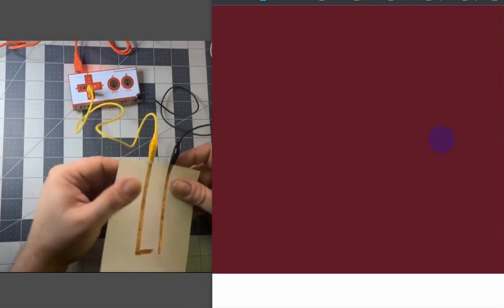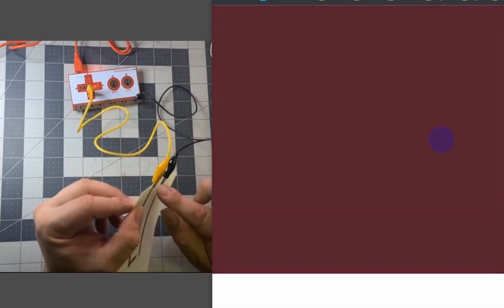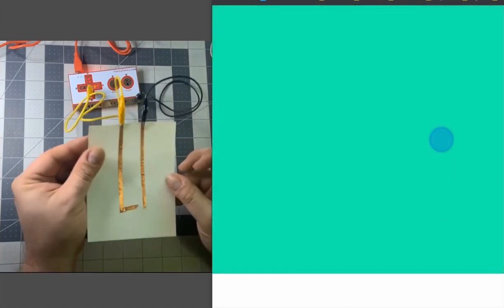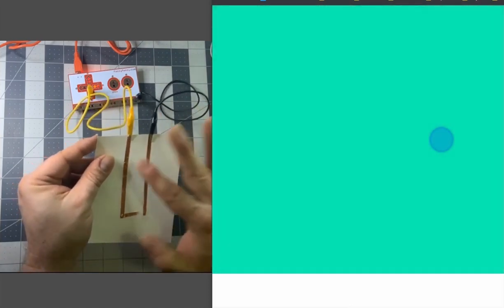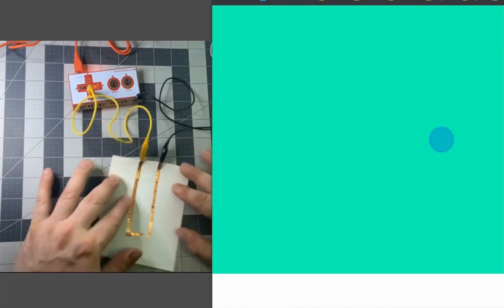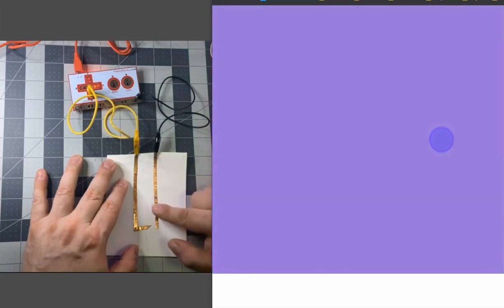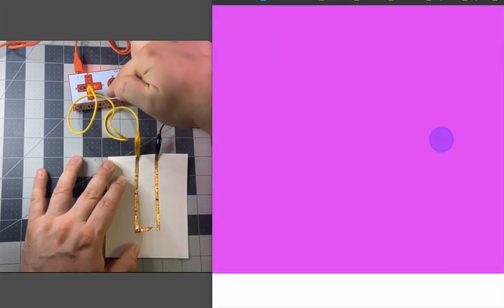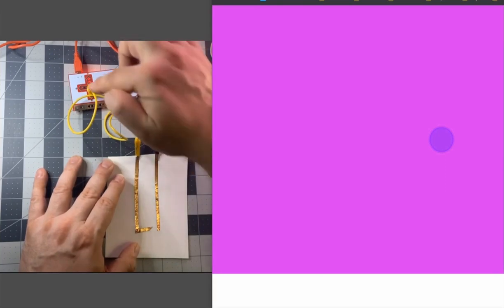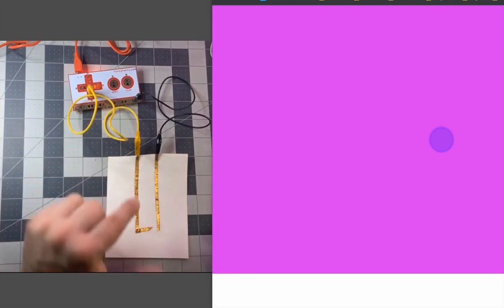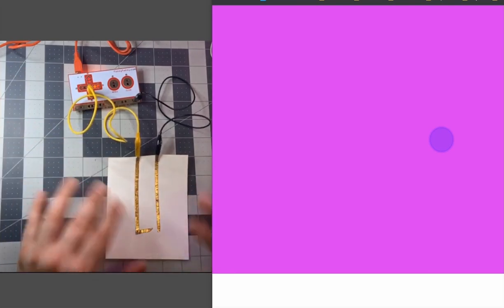Okay. It's also important to understand that the teeth in those alligator clips dig into the copper. And no matter what material we use here, we should be able to do that. So from this, what we could actually do is create multiple buttons that are connected to the ground. You only need one ground wire, and that's why the earth on the Makey is one long one. They're all connected, but each of the keystroke buttons is its own circuit. So as you touch those individually, that's where that would work.